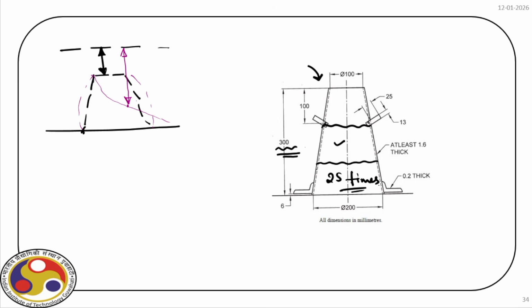This is a very common test often used at construction sites to check workability. It is very easy to check, and with the help of this height, the workability of the concrete is checked. There are some codal provisions based on this height, whether we have workable concrete, and to what extent is governed by this height, right?